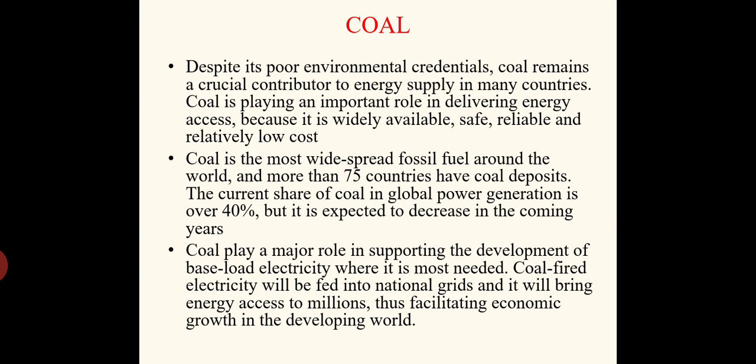If you want to operate a peak load plant, it has to start instantly and it has to stop within a limited time. To make that possible, the only option is to go for oil or natural gas as the fuel. If coal is being used, once it is stopped, it requires a very large time to start again. For the initial combustion, a large amount of oxygen is required, and a large amount of extra heat is to be supplied to initiate the combustion.